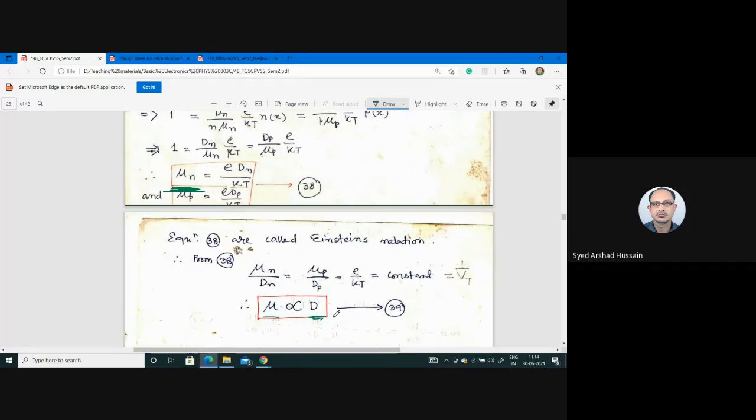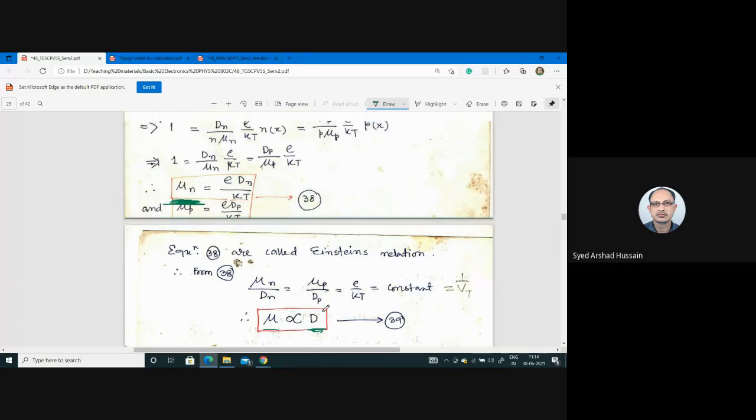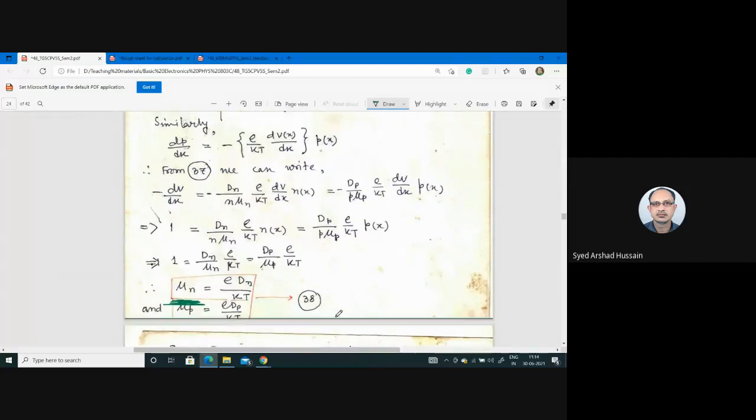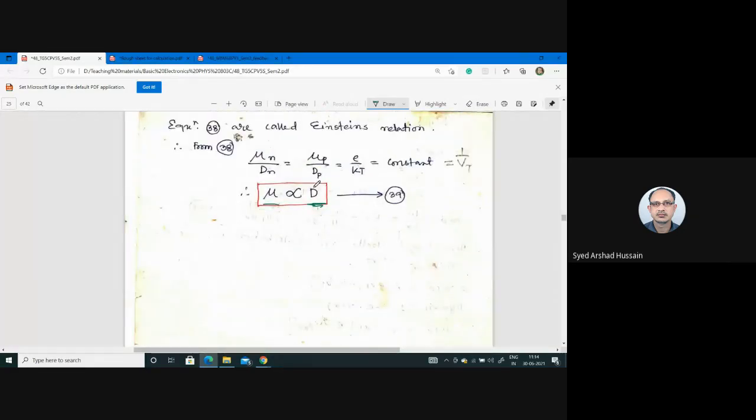Diffusion mainly arises because, due to current in a semiconductor, two types of currents are there. Okay, one is due to conduction, or mobility is related to conduction. Okay, this is one part, and then another is due to inhomogeneous distribution of carriers within a semiconductor. Diffusion occurs from the higher concentration side to the lower concentration side. If you imagine a concentration gradient across any plane within the semiconductor, D mainly arises from this diffusion, and it's a characteristic of the material, and mu is also a characteristic of the material because it depends on the doping.